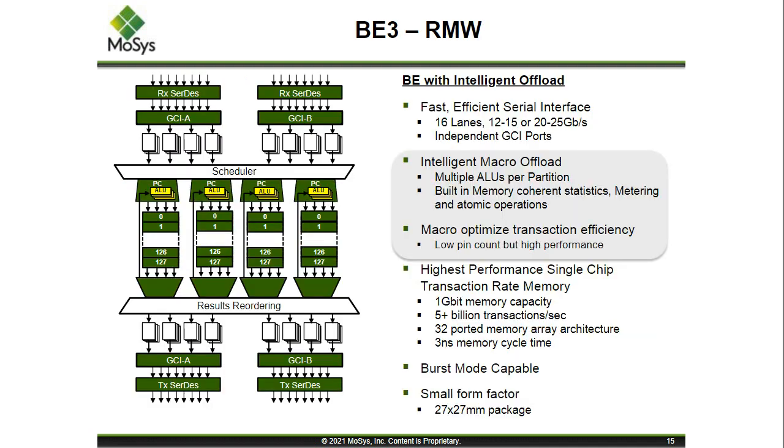And then the second one is even more of a release for the host or processor. It's an offload where you can do something similar to an RMW, where you would normally have to do a read, wait for the structure to come back, modify it, and then write it back, right? So there's a couple of bus transactions that would have to occur and some processing time that the host would then have to take up as well.